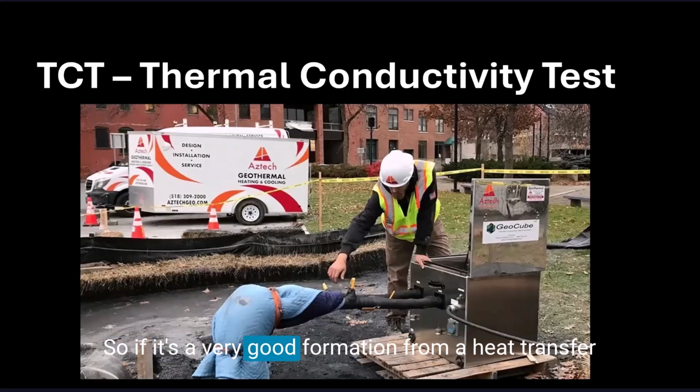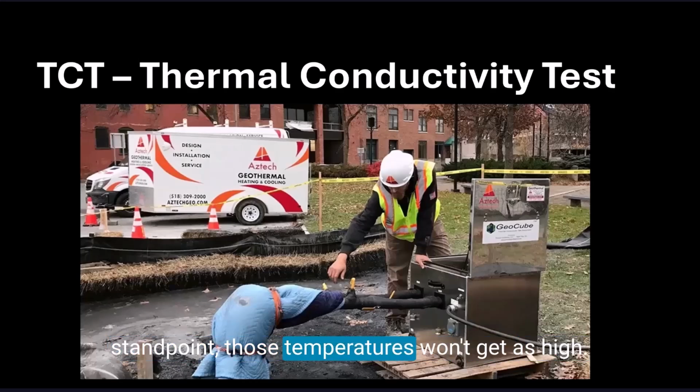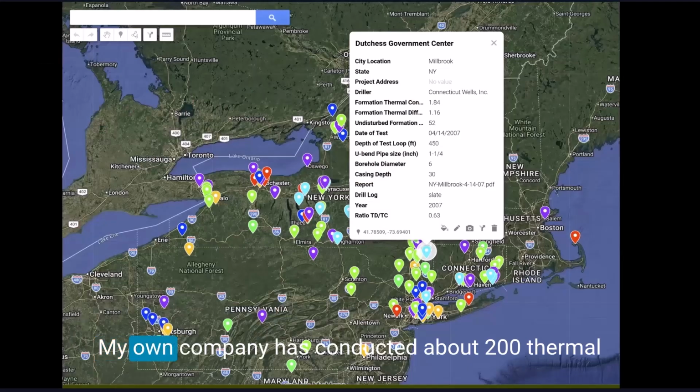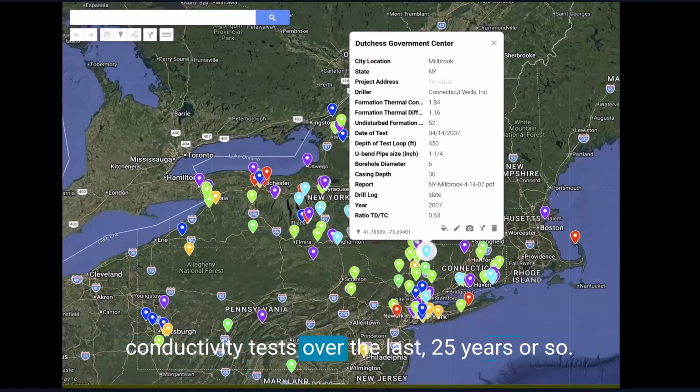If it's a very good formation from a heat transfer standpoint, those temperatures won't get as high. If it's not so good, you'll notice the temperatures getting higher. From that data, we can back out those parameters, the conductivity, and to some degree, the diffusivity values. My own company has conducted about 200 thermal conductivity tests over the last 25 years or so.